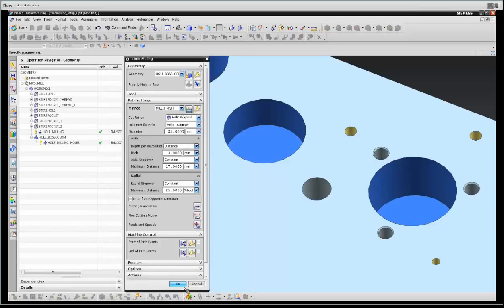Then that might be a good way to do that, to output points. But we do output circle records for all this. It's just continually larger radius circles as they go out and are tangent to one another, so you get a nice smooth flow out. But I think this is a very nice way for cutting these larger features.